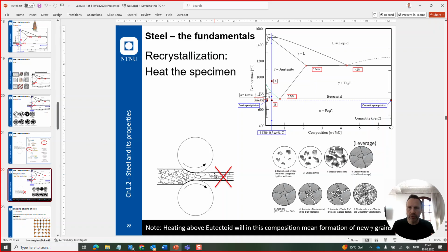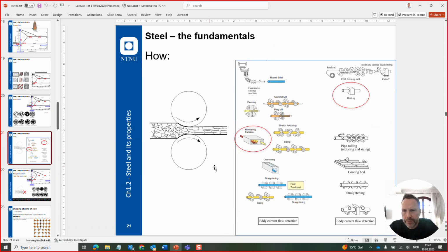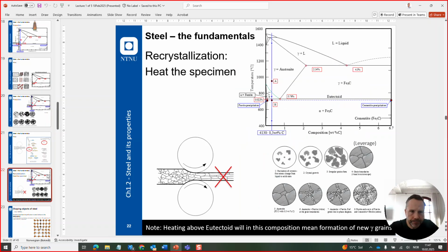That's why, as we see on the right side here, on a frequent basis, you reheat it to keep preventing it from going down. You keep it at this state, you work the whole specimen of pipe up here, you keep the temperature. As it goes down, it will keep as if the grains never were elongated, or so you rework the microstructure.